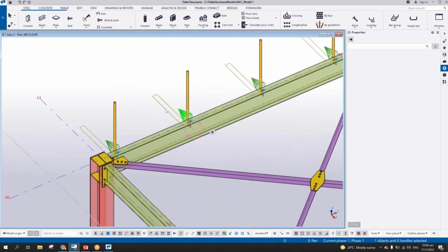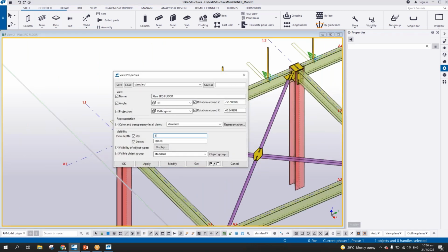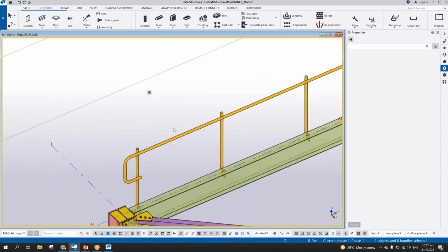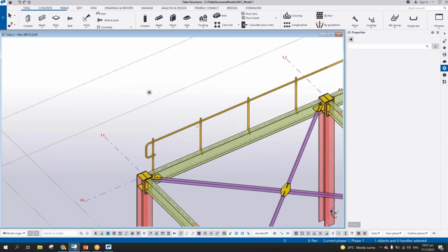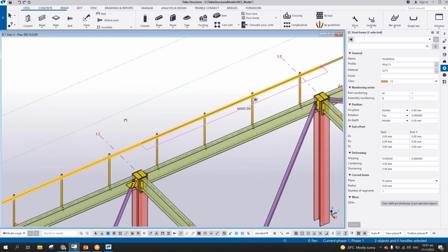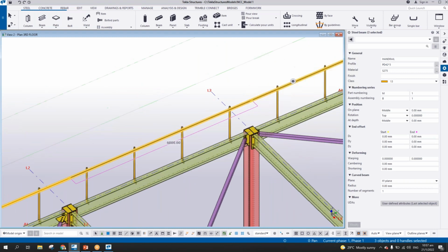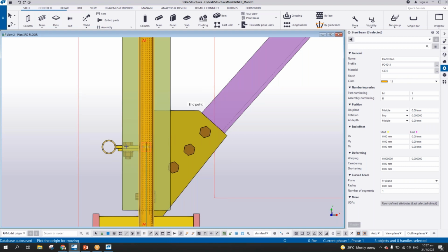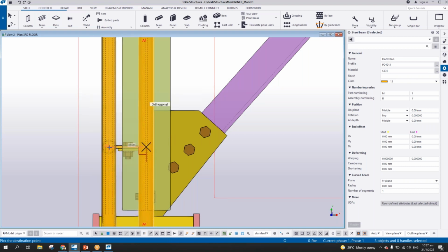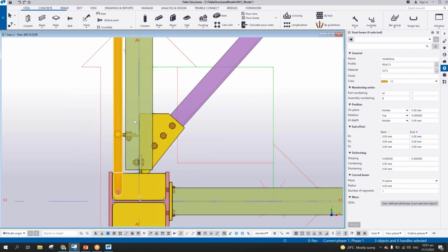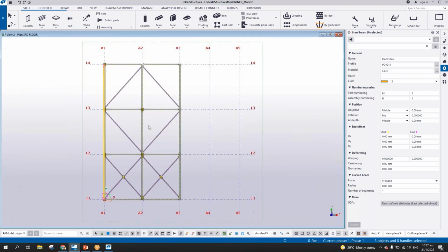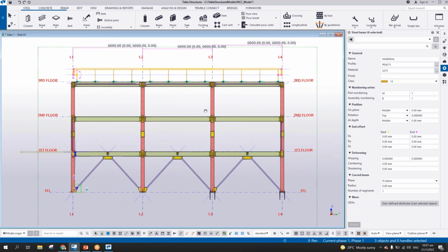Okay. We need to increase this one to 1,200 so that we can see the top rail. Yeah, you will not be able to see the top rail because of the view depth. So here, I'm going to move this one 110 outside. Okay? Like what we did earlier, we need to move from this point to here, 110. There you go.